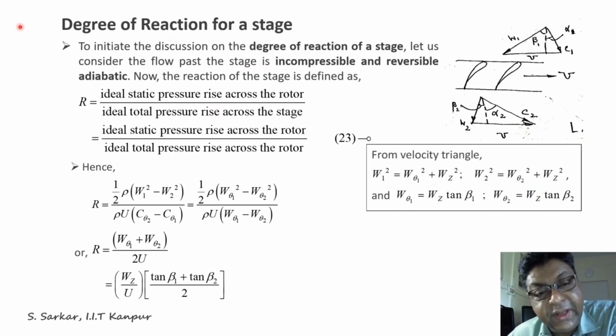To initiate the discussion on degree of reaction of a stage, let us consider the flow past a stage to be incompressible and isentropic, that is, reversible and adiabatic.